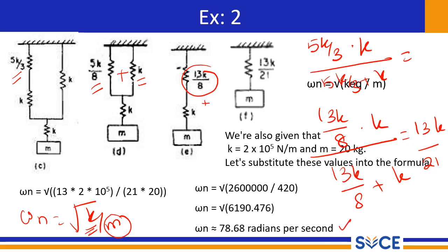So what we understand from this problem is, if there are n number of springs connected in series and parallel, we have to convert them stage by stage to an equivalent stiffness. Then at last the single equivalent stiffness of the system will be arrived at. Using that we can calculate the natural frequency for the entire system. Let's go for some practical application in the next slide.